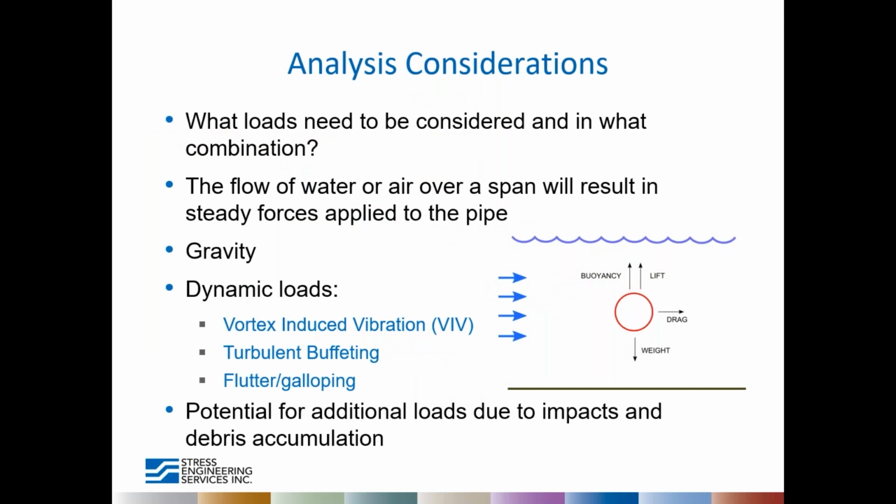So when we look at pipes, we need to consider what loads we're going to look at in which combinations. And the picture on this page is going to occur repeatedly in this presentation because it's helpful for a lot of the different topics. So the water or airflow over a span will give you drag forces and lift forces. The drag is almost always important for spans in flowing water. But it can also be important when your spans are exposed to high-speed winds.